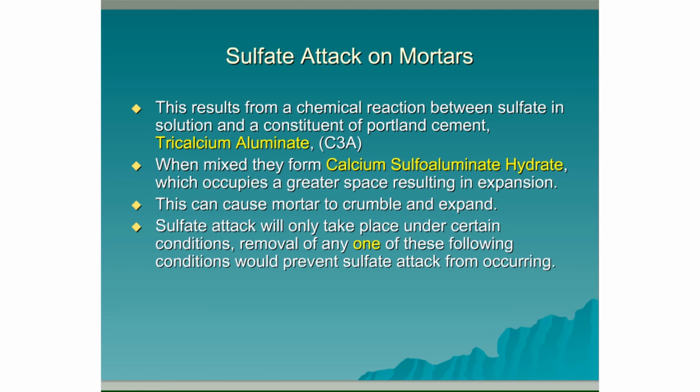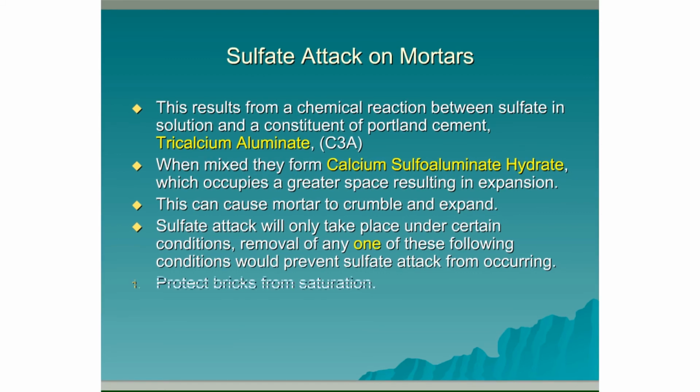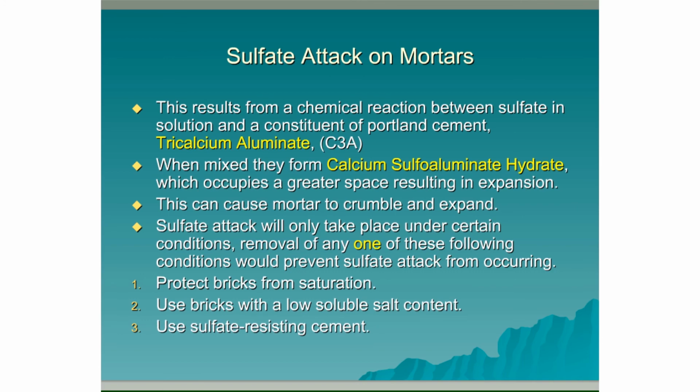Sulfate attack will only take place under certain conditions. Removal of any one of these following conditions would prevent sulfate attack from occurring. 1. Protect bricks from saturation. 2. Use bricks with a low soluble salt content. Or 3. Use sulfate resisting cement.